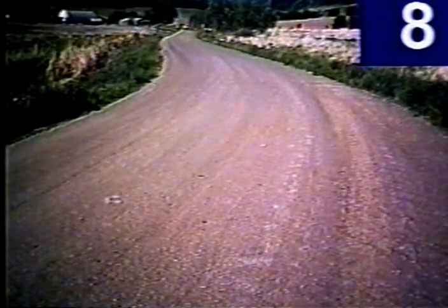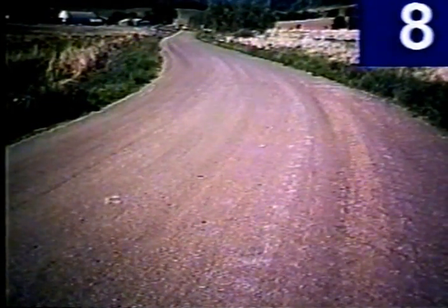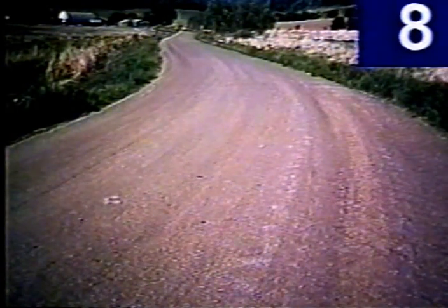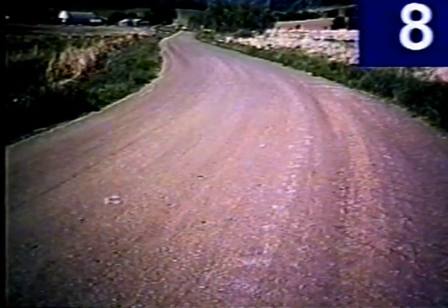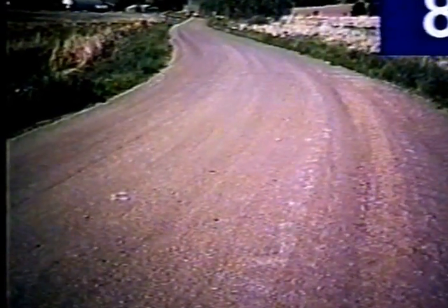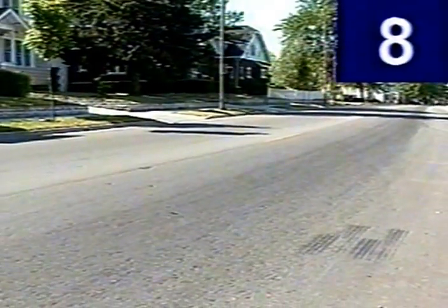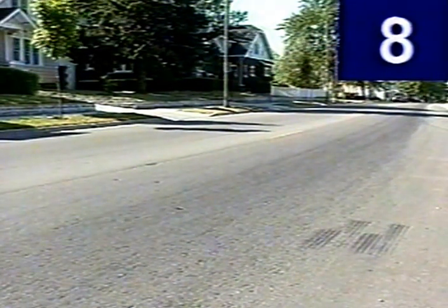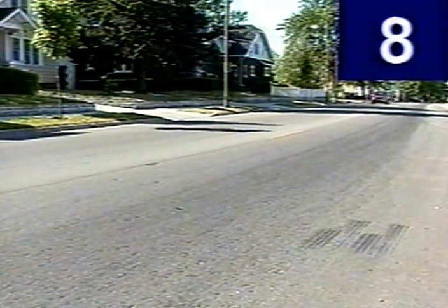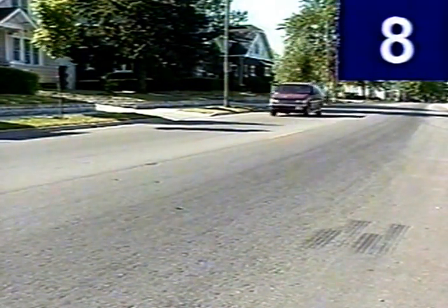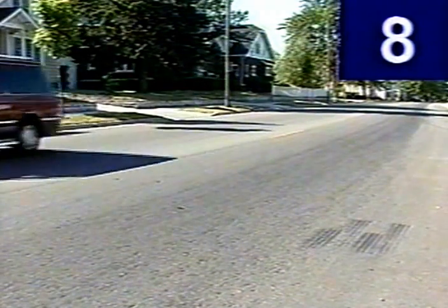Another example of a pavement that we would put in an 8 category is a new surface using a road mix. A road mix surface, it's in good condition, requires no maintenance, and would be rated an 8. Another example of a pavement that we would rate an 8, it has some life on it. It's not a recent overlay or brand new, but it is in excellent condition, and we would rate this pavement an 8.